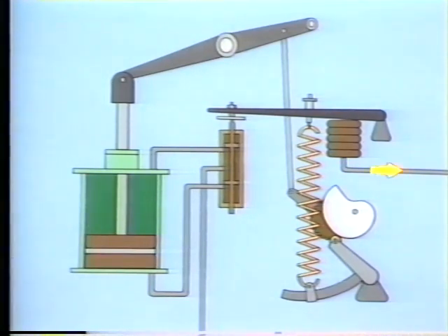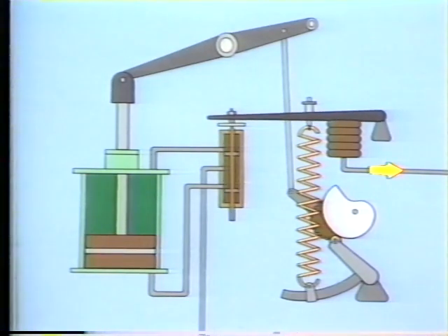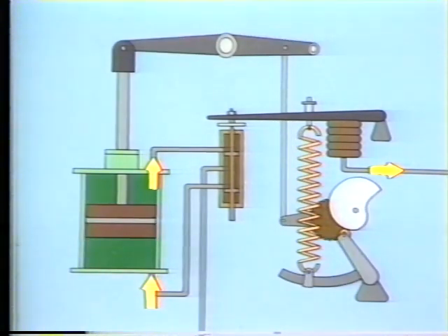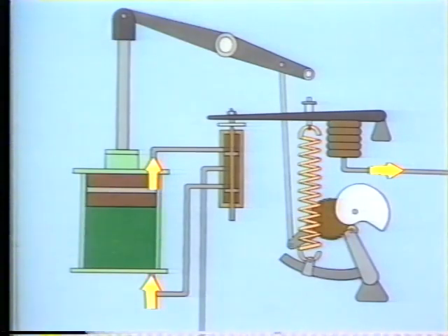If control air decreases, the bellows contracts, lowering the balance beam and pilot valve stem. This reverses the flow of supply air to and from the piston actuator, moving the piston and piston rod in the other direction. Now, so far we've seen how a positioner responds to control air by directing supply air to a piston actuator to move the piston and piston rod either up or down.